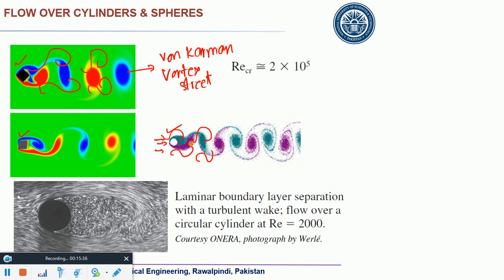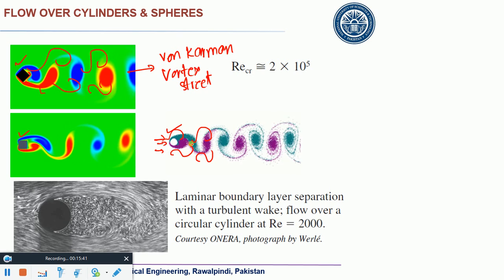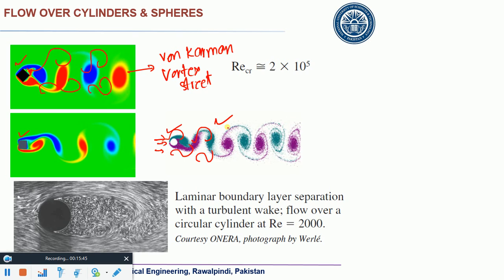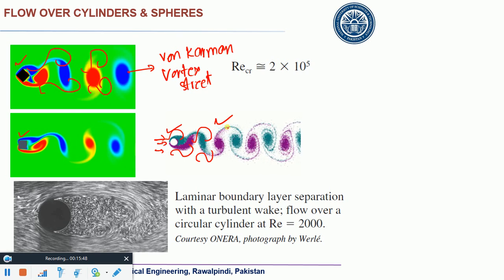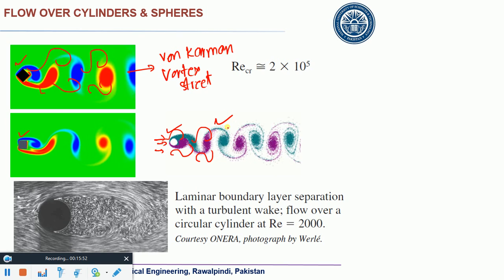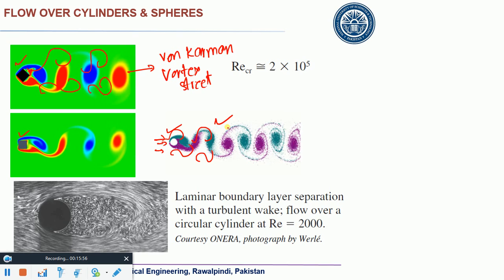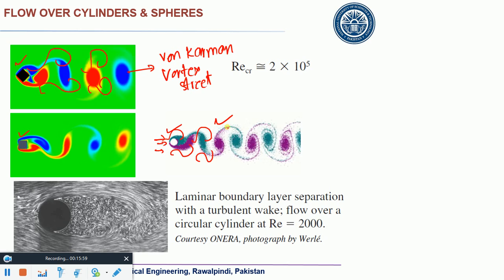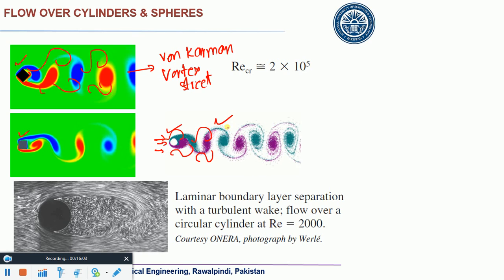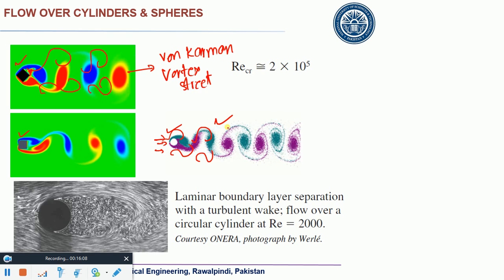You might have seen the shaking of buildings and shaking of bridges, isn't it? That vibration of buildings. Okay. So what is that? That occurs due to the formation of these vortices. It is just like that. Each and every vortex pushes the structure and then it moves on. It gives a push to the structure and then it moves on. It means that the structure would have continuously oscillating forces applied on it, that building or any pipe or anything else.